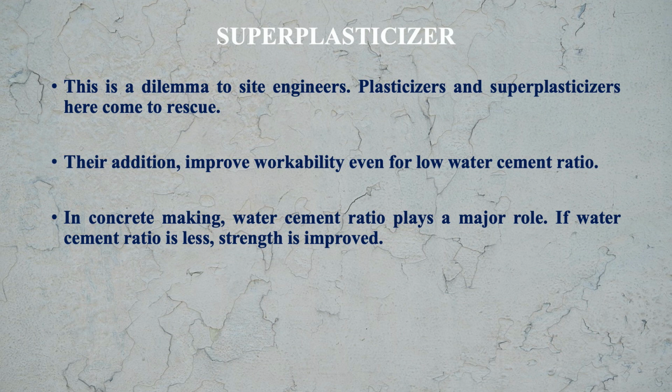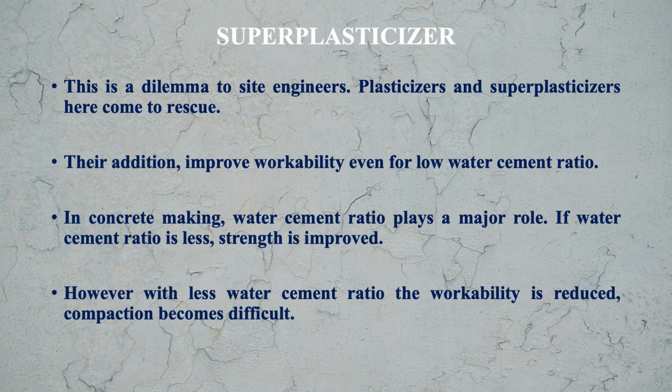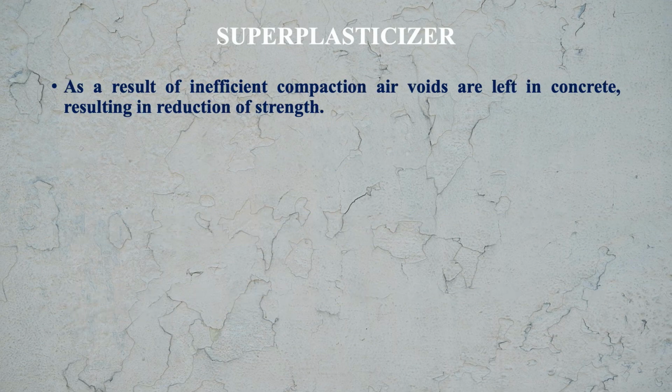In concrete making, water cement ratio plays a major role. If water cement ratio is less, strength is improved. However, with less water cement ratio, the workability is reduced, compaction becomes difficult. As a result of inefficient compaction, air voids are left in concrete, resulting in reduction of strength.